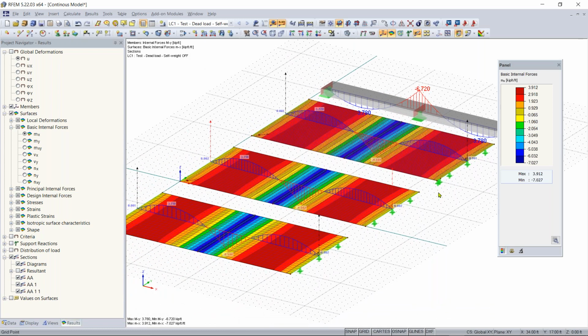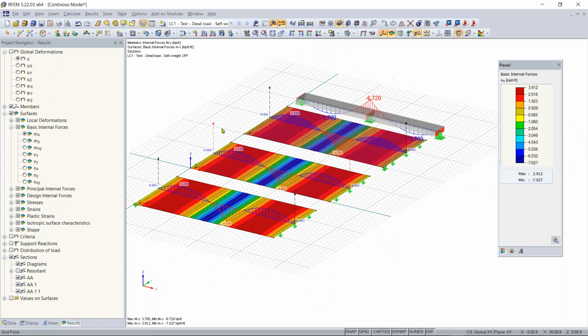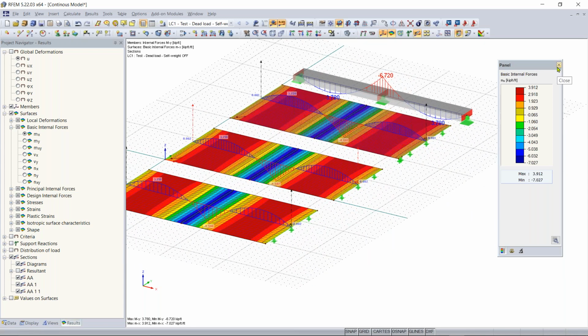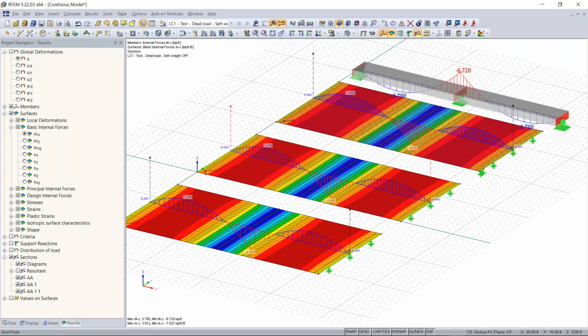Yes, it is important, a thin or a thick plate. When we're getting into a surface element whose thickness is relatively comparable to its width, then you would want to convert this to a solid element, a 3D solid element. We have some recommendations in our FAQ of when you need to consider a solid element instead of a surface element in order to get accurate results.